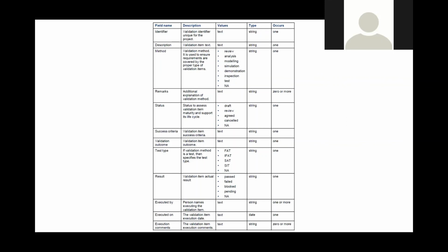In the verification, you mostly have design documentation or surveys, and in validation, in our field, in the railway industry, you'll have mostly physical FAT, SAT, and control systems, physical as-builts, physical red line markups. You'll have inspection and test reports, you have got physical structural certifications, structural proof testings, and whatnot as your physical evidence of constructing to the requirement.